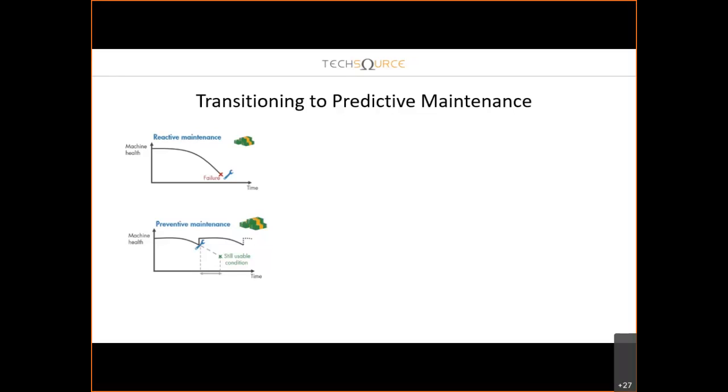One big challenge with preventive maintenance is determining when to do the maintenance. Since you don't know when the failure will occur, you have to be conservative in your planning, especially if you're operating safety critical equipment. But by scheduling maintenance very early, you are wasting machine life which is still usable, and this also adds to your cost. However, if you can predict when a machine failure will occur, you can schedule maintenance right before it. The good news is that predictive maintenance lets you estimate the time to failure. It also pinpoints problems in your complex machinery and helps you identify what part needs to be fixed. This way, you can minimize downtime and maximize equipment lifetime.